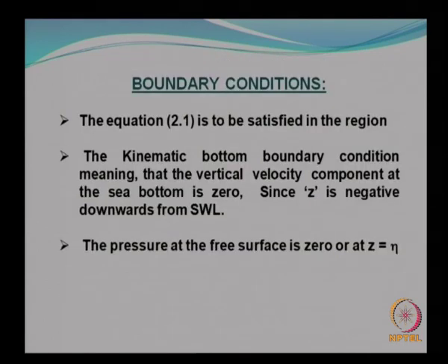Now, the boundary conditions, as I said earlier, please remember the equation numbers. Equation 2.1, that is nothing but the Laplace equation, has to be satisfied in the region which I have already said. The pressure at the free surface is 0. When I say pressure at the free surface is 0, that means z equal to eta.